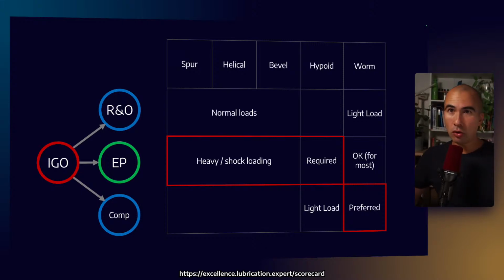Now, just a note on PAGs, and again, if it ever came up in the exam, the thing about PAGs is they have extremely good performance, very good oxidation stability, and a very high degree of lubricity. The challenge with PAGs is that they don't play nice with other lubricants. They tend to be quite incompatible, especially with things like the PAOs. So they're not very miscible.